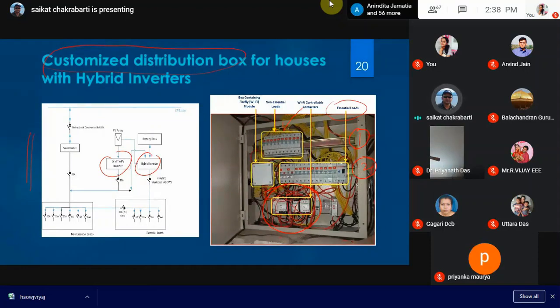For example, the wireless switches, we had a very strange problem. The polarities were getting reversed. So then we figured out it was actually connected to a fan, ceiling fan. So the moment you switch on a fan, there's a back EMF that was switching off the switch, that transient. So we had to take care of that. So those are challenges that you have to go through when you are implementing these new technologies.